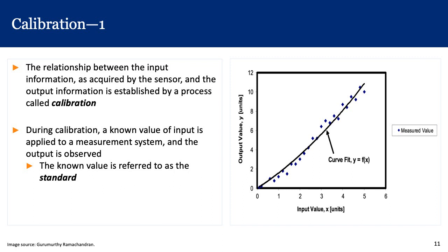Once we have this curve, we can use this calibrated rotameter to measure any unknown value of flow rate. We would put in an unknown value of the airflow, attach it to the bottom of the rotameter, and find out how much distance the float traveled. Then we say, oh, the float traveled 6 centimeters. Therefore, the flow rate, according to this calibration curve, is around 3.5 liters per minute. That's the way the calibration curve is used to determine the flow rate through this rotameter.